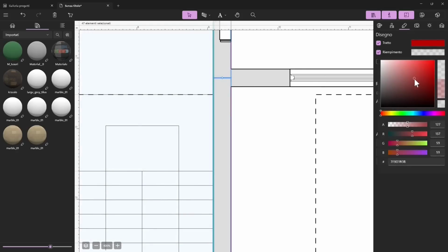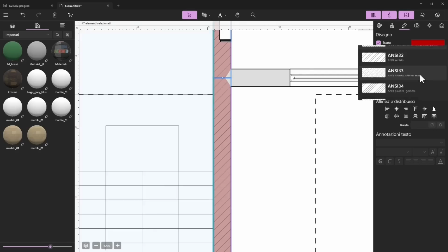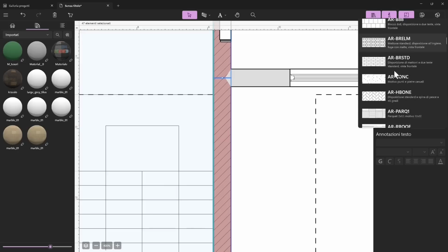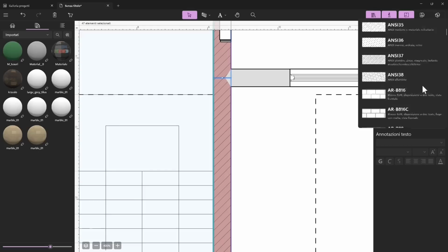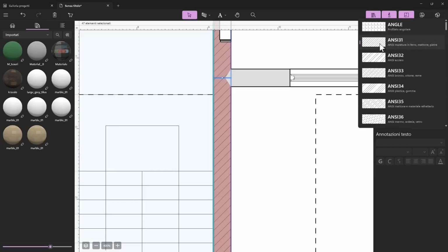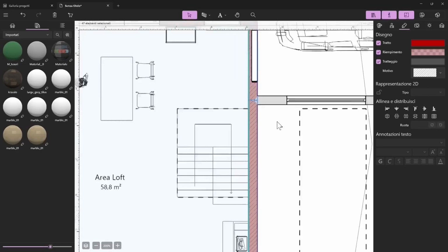And then I can make a different fill, a different hatch or a solid fill in that wall. Or I can apply a pattern. I can apply a hatch. So this is the hatch right here, with these specific codes. So you can apply some specific hatch, or just a simple solid fill, depending. This is used for walls, usually for brick walls, a representation like this.